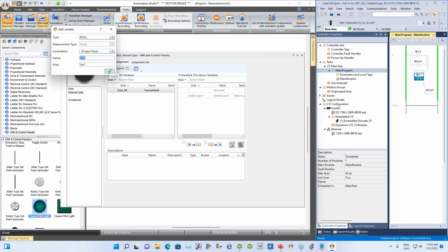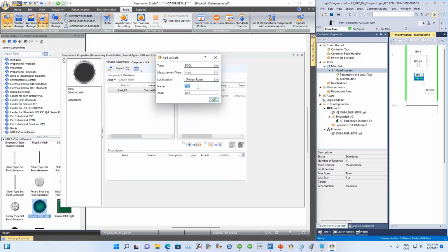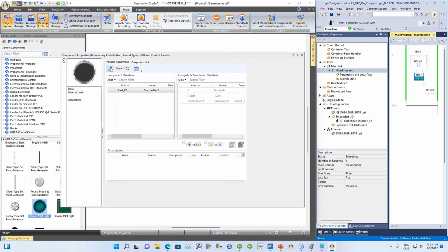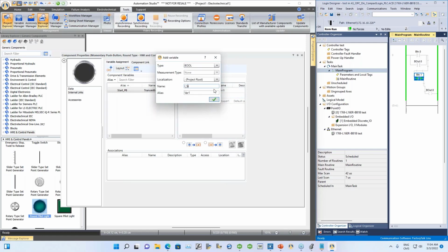So I'm going to just create here variables in Automation Studio, Boolean. I'm going to use a specific syntax in Automation Studio for these registers, which is just going to help me later on to do filtering. So all my inputs, I put I underscore and give the name of the input. So this is start. I need also to create a stop. So I'm going to create a stop register in Automation Studio. And then I'm going to create one for the output, the light. I'm going to call it, let's say, L light, output light, okay?